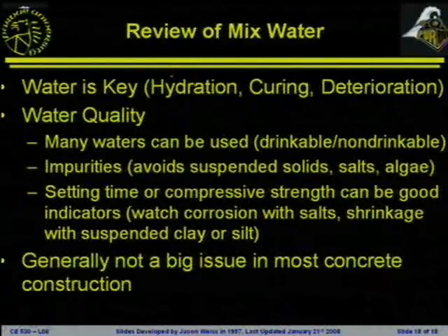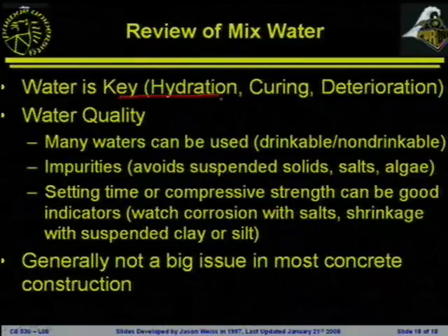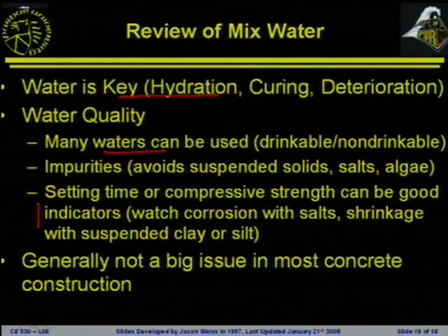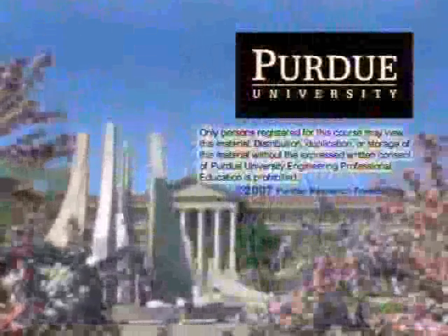So a review of mixed water in the last 10 seconds. Water is a key, hydration and degradation. You want to remove any impurities. The biggest things that you'll be looking at are deleterious reactions and setting time. Most of the time, not a big issue. Any questions?